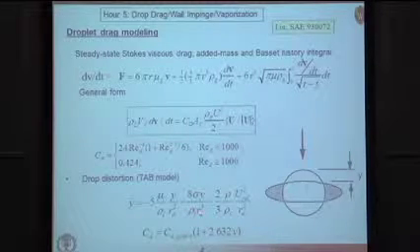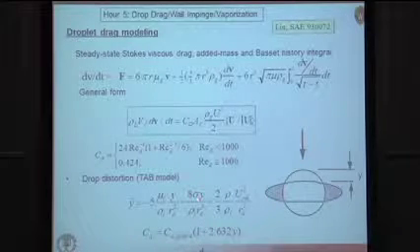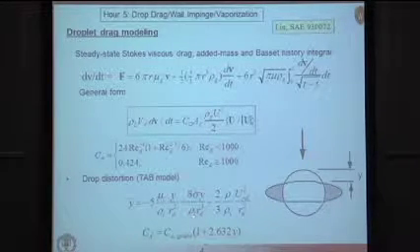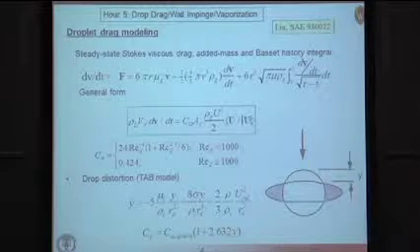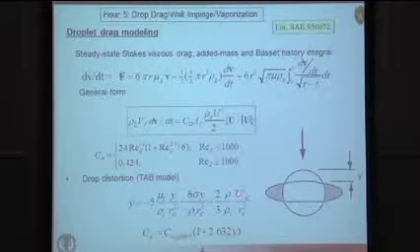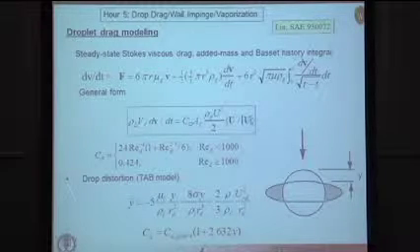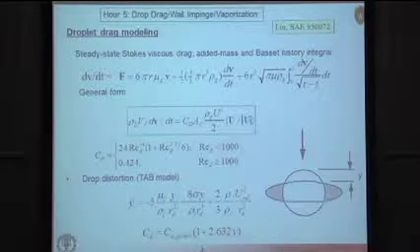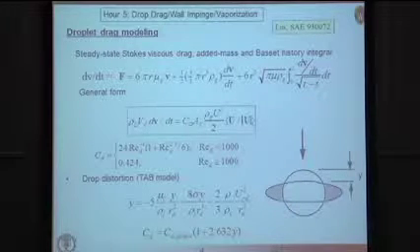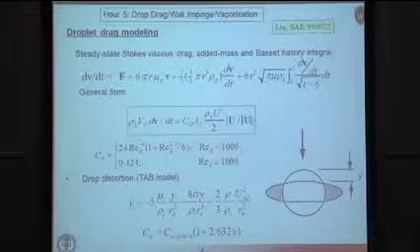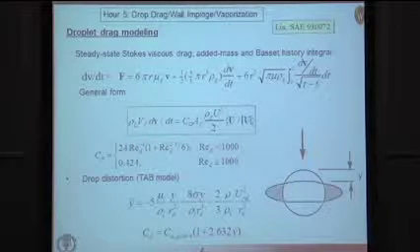And then there's a term due to surface tension, which is like a spring mass system. So this would be the spring in the spring mass system, surface tension, liquid density. And then finally the forcing function, which is that dynamic pressure term, the relative velocity between the drop and the gas. And here we have the gas density and the liquid density. So if you solve this equation as a function of time, you can calculate essentially how distorted the drop becomes. And you can store that as part of the characteristics that describe this particular assemblage of drops in your parcel.